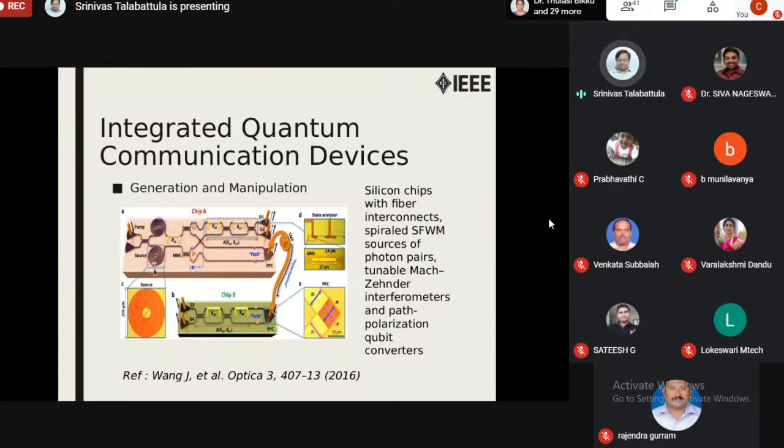In these 2, it may not be very apparent, but both these signals are there. Both the qubits are in this loop, and they can pass through this set of devices. You can say these are interferometric devices. There's a chip A and chip B, and you can also communicate between chip 1 and 2. There is also a source of information which has a loop of fiber and so forth. You also see that there are couplers. The waveguides are intersecting, and there are couplers to exchange photons between them. Of course, you cannot divide the photon, but there's a probability that light is exchanged.